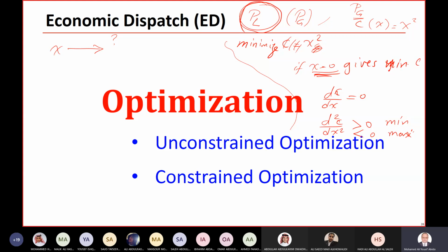Or disconnect the factory. So in this case, the power system operator should respond to this. Okay, what is in his hand. Of course, we are not talking about load shedding or the power system operator. Of course, the power system operator also has the authority to switch off loads if the system stability comes into question. If the system becomes unstable or the frequency violates the limits, in this case we can go to load shedding.